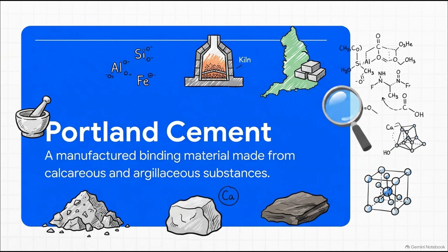The key takeaway for your exam, though, is the recipe. It is a highly engineered mix of calcareous materials. Think calcium and magnesium stuff, like limestone, and argillaceous materials. Those are your silica, alumina, and iron oxides, mostly found in clay or shale.